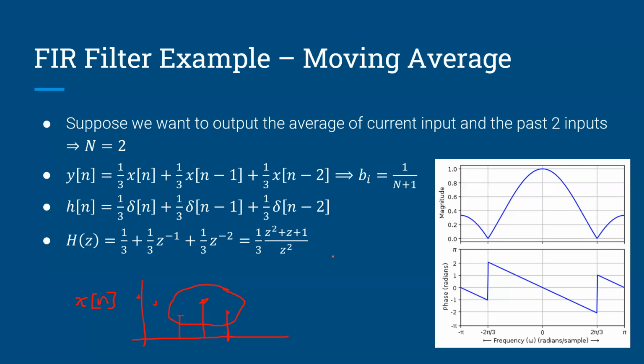And then if you look at the frequency response of this, you can kind of ignore this part. That's just negative frequency. But if you start here, you see it has a low pass kind of shape. And then at some point it goes to exactly 0 and it starts rising back up. That's kind of a property of digital filters. Also, if you look at the phase